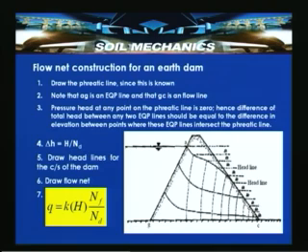So, this being known to us, note that in this cross section, a dam is shown here, and AG is an equipotential line and GC is a flow line. This is the bottommost flow line, because the flow cannot cross the impervious base, it flows along the impervious base. So, with that in mind, GC is a flow line and AB is an equipotential line.